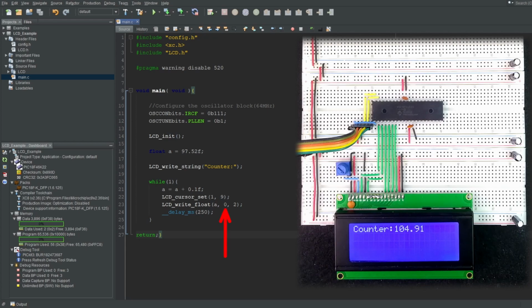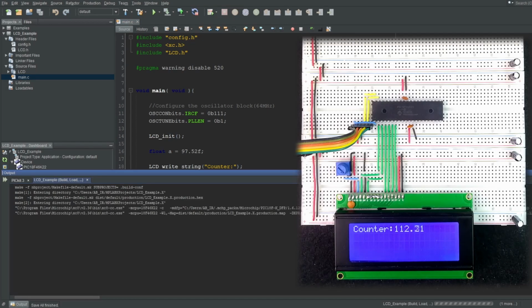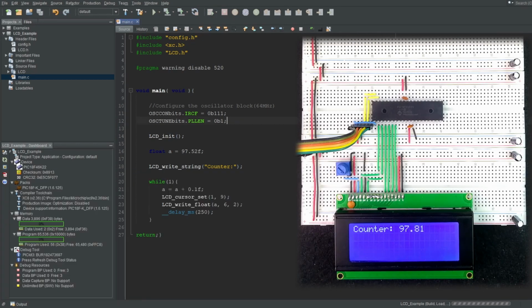This is where the offset variable comes in. This value offsets the least significant digit of the variable to be written. Let me give it an offset of 6 instead and program again. As you can see, the least significant digit is written with a 6-column offset, and the digits are growing to the left. But be careful, if the total digit count of the number ends up the same or bigger than the offset, the digits will start to grow towards the right again. Also, even if you give an offset, after the function is complete, the cursor will point to the next column after the variable.